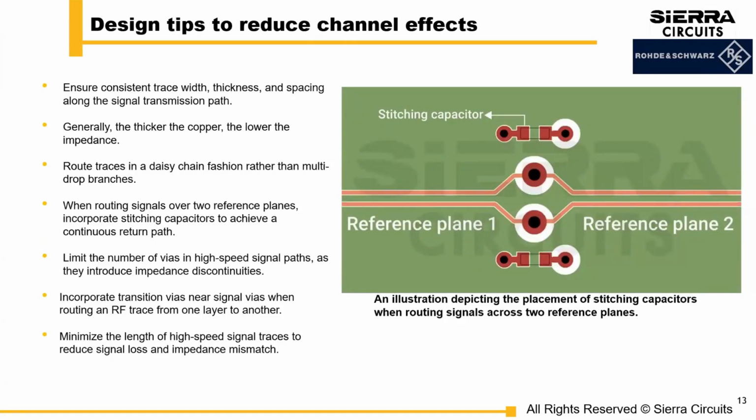So here are some design tips to reduce channel effects. Again, Mike will be talking about the channel effect. To minimize jitter and insertion loss during signal transmission through a channel, you want to ensure consistent trace width, thickness, spacing throughout the signal path.